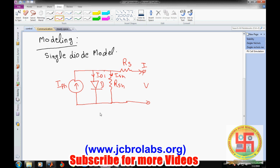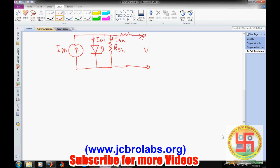So the equation of I, in order to do modeling, is I equals IPH, because all these parallel currents are being subtracted from IPH. So IPH minus the diode current. The normal diode current is given by I naught times e to the power of (V plus I times RS) divided by (A times VT), minus 1. It is very easy. So it is the normal diode current.